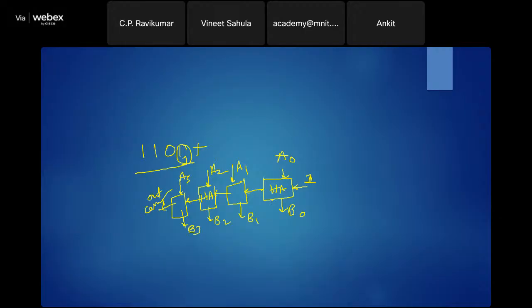Okay. So that's the reason why we don't need any full adder. We only need half adders. Right. Everything is a half adder. Okay. The advantage of this design is that it is regular, and as a result, you can design one module and repeat it, right?